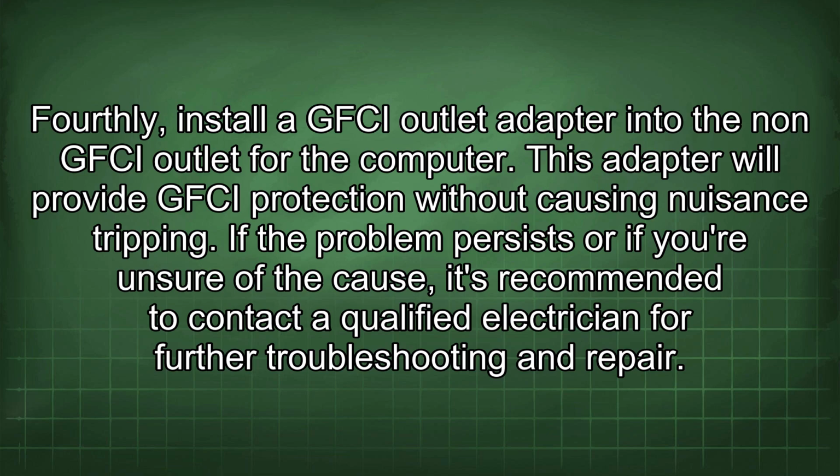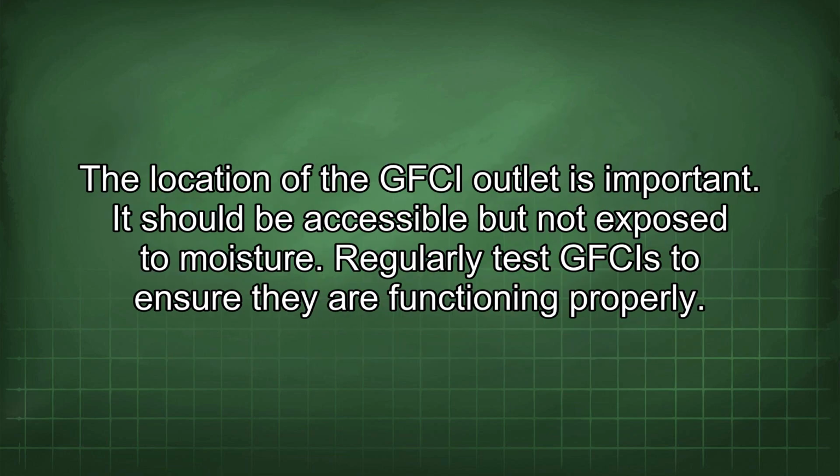Fourthly, install a GFCI outlet adapter into the non-GFCI outlet for the computer. This adapter will provide GFCI protection without causing nuisance tripping. If the problem persists or if you're unsure of the cause, it's recommended to contact a qualified electrician for further troubleshooting and repair. The location of the GFCI outlet is important.